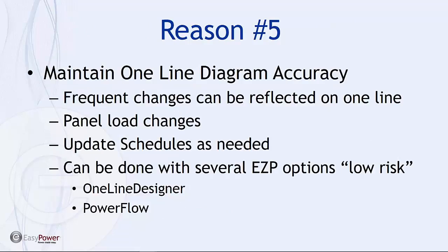One of the reasons that I would want the file as a client, and that I think a consulting firm should share the file, is that first and foremost, in both OSHA requirements and NFPA requirements, is the need to maintain a current one-line diagram. And whether changes are big or small, having some ability to update that data file benefits the customer in the long run. Some of these may be reflected in panel load changes.